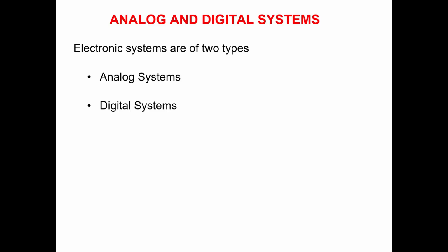While a digital system is one in which the voltage levels assume a finite number of distinct values. In virtually all modern digital circuits, there are just two distinct voltage levels. However, each voltage level in a particular digital system can actually be a narrow band or range of voltages.